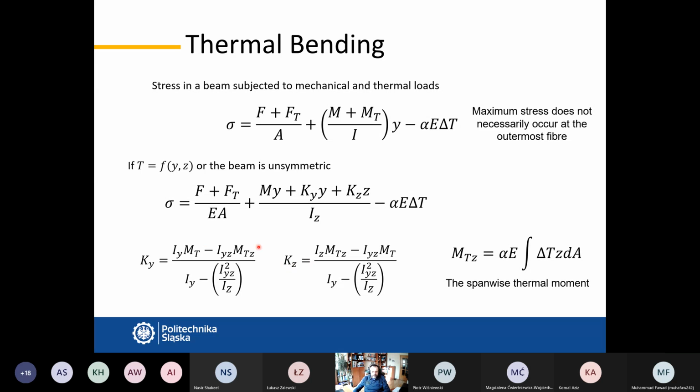So we can see what is the amount of moment in z direction, what is the moment. So we have unsymmetric bending actually. So slightly the beam is slightly bent into z direction, slightly bent into y direction. So we have to combine them together, as you may also remember from your structural material course, if you recall that asymmetric bending.